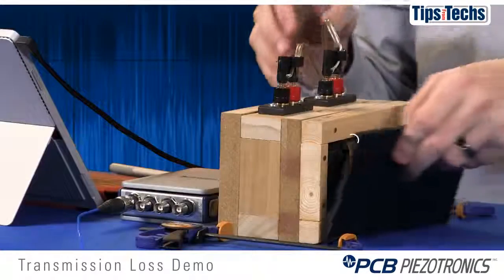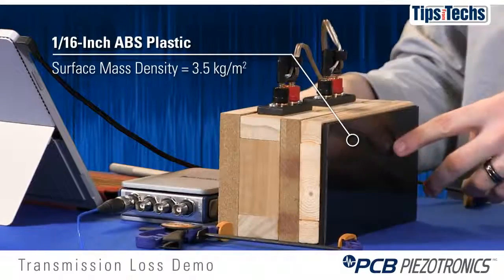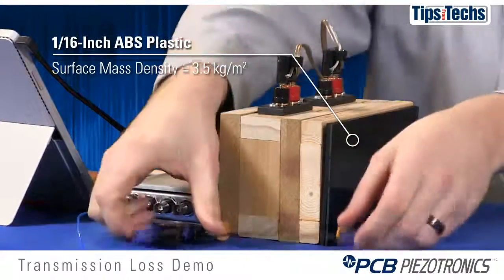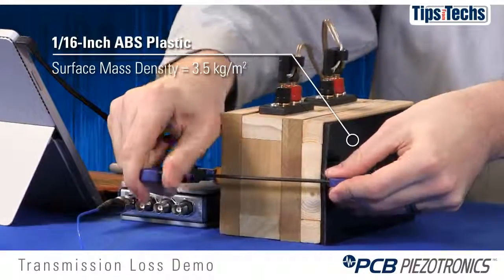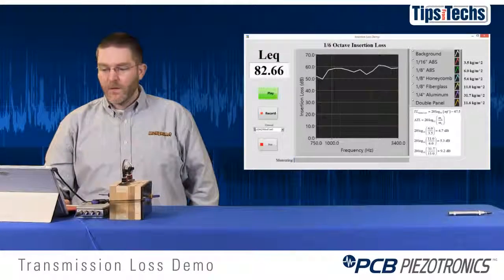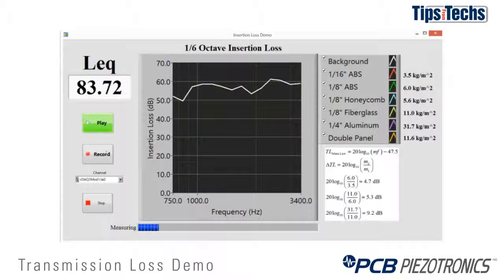We'll start with the thinnest material. This is the 1/16 inch ABS. It has a surface mass density of about 3.5 kilograms per meter squared. You can already hear the difference in the quality of the sound coming through that panel. And there is a plot of the insertion loss. So at 750 hertz we have almost no insertion loss with this panel, and at 3400 hertz we have almost 30 decibels of insertion loss.